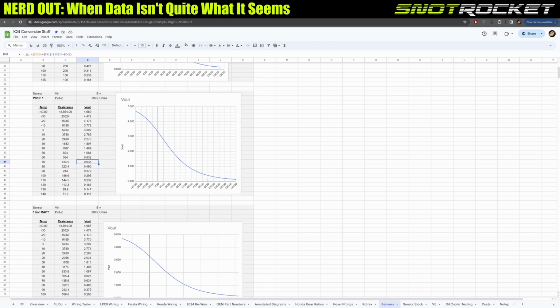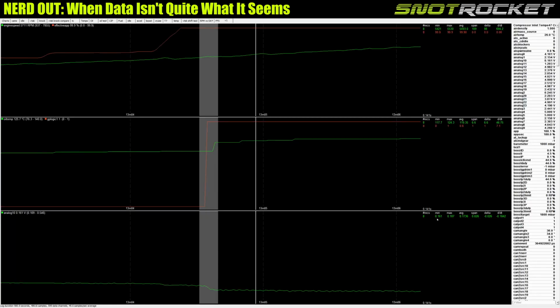And that's not good. That means the voltage change, and here's a chart here, right? So at 100 degrees, the voltage is 0.295, and at 110, it only drops to 0.0232. Now, as you saw on that previous chart here, a 0.026 change in voltage, which is basically the noise that the VTEC is introducing to the electrics of the car, is resulting in a temperature shift here from 117 degrees to 124.